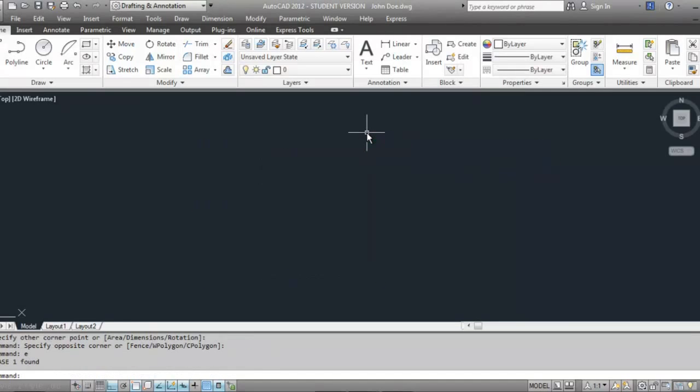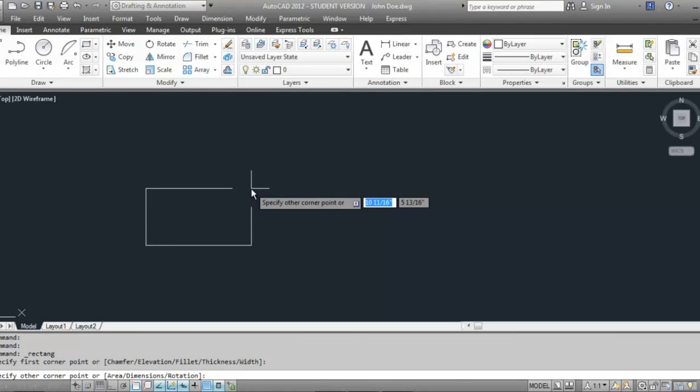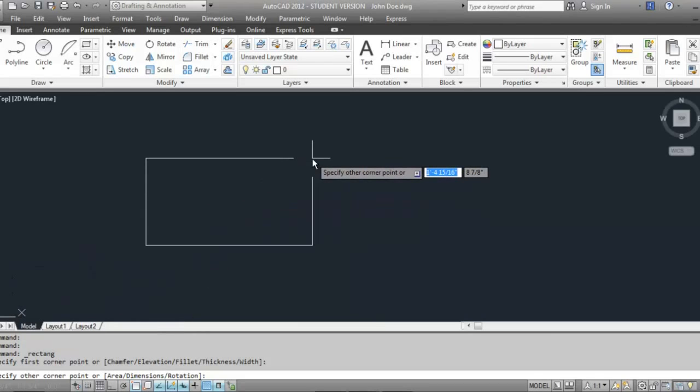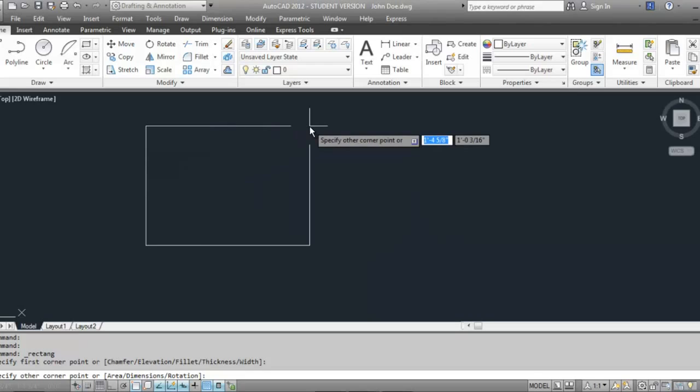If you want to specify a rectangle that is say 4 inches by 3 inches, then this is what you have to do. You go to rectangle, you click to start the rectangle. Now you have to be very particular about what measurement you want to put first. Because CAD is using the Cartesian system, you should remember that you always put the horizontal dimension or the x-axis dimension first and then the y dimension. When you want to specify a specific point, I want to specify a point away diagonally across from the first point we started the rectangle from, you have to first type the @ symbol.